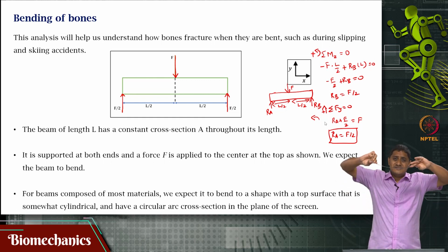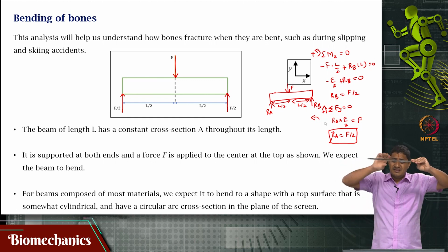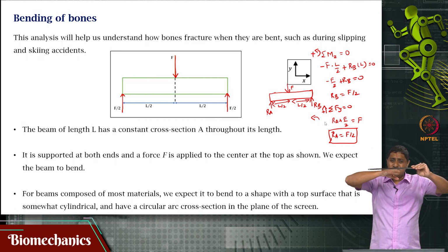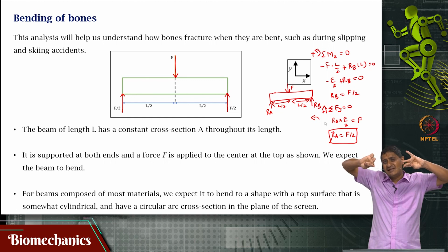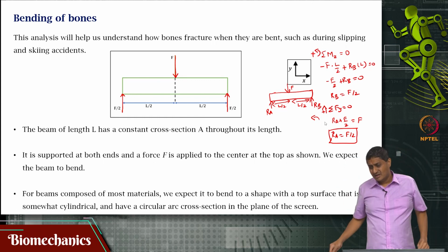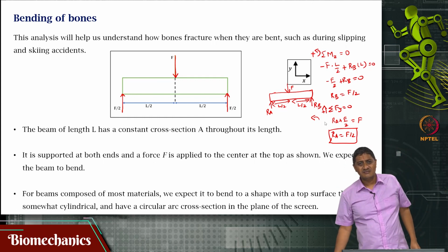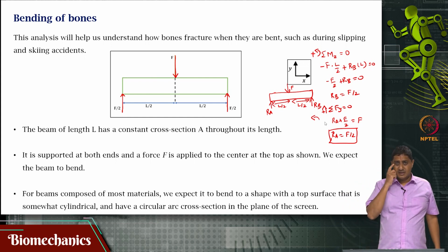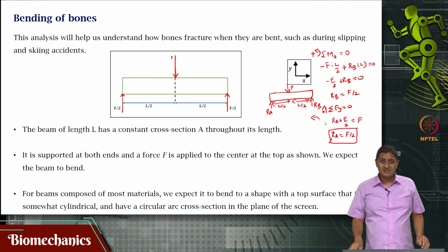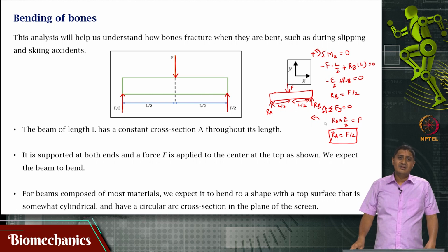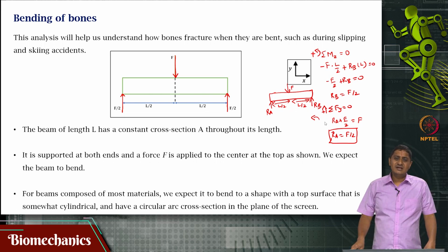In that case, as you go from the bottom to the top, at the bottom the length will be higher, and at the top the length will be much lower, and somewhere in the middle, not necessarily exactly in the middle, there will be a particular point at which the length before bending and the length after bending will remain the same.